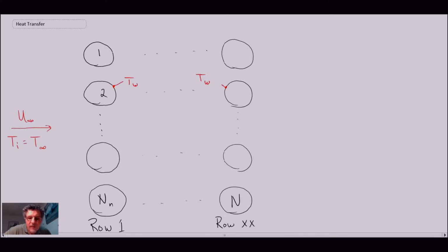However, sometimes you may have fluid going through a phase change, such as in a condensing unit. In that case, it would be a fair approximation to say that the fluid on the inside of the tube bundle was all at the same temperature. So that's the wall temperature. Another thing that we will say, and we saw this in the previous segment, is that the spacing between the tubes themselves, going from center line to center line, will be S subscript N, denoting the normal direction to the flow.